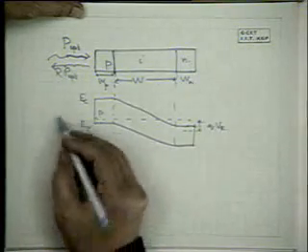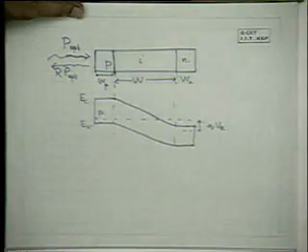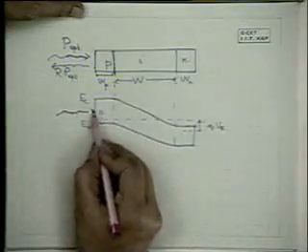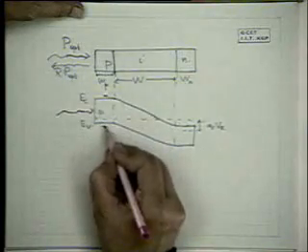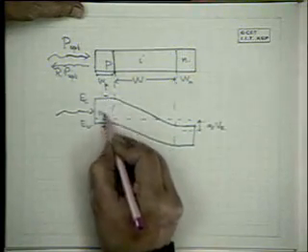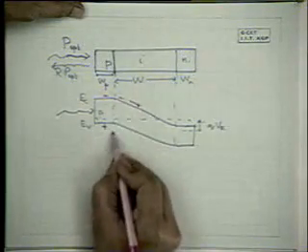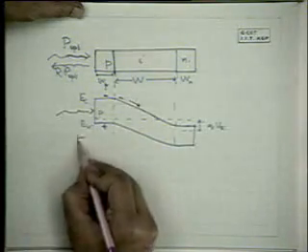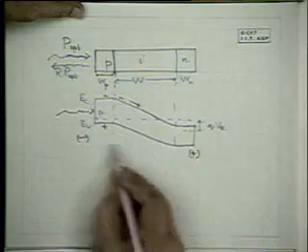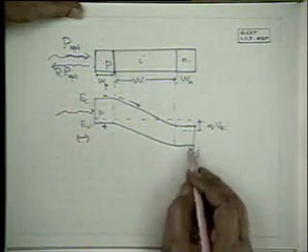And when light is incident, if electron hole pairs are created here, if they are created within this diffusion distance, then they will diffuse. This is negative and this is positive, so the holes will migrate towards the negative electrode, electrons towards the positive electrode.